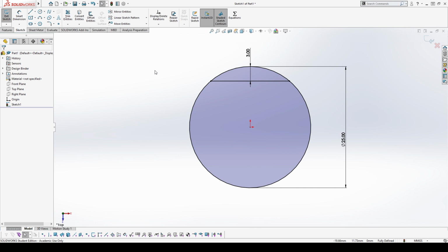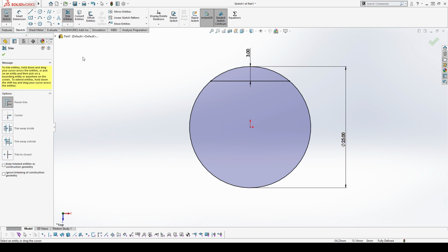But one of the things that I like to do, and it can be fairly good design practice, is to communicate that the shaft is still circular to start, and we're cutting away part of it. Without us knowing about the manufacturing process ahead of time, it might not be super obvious.